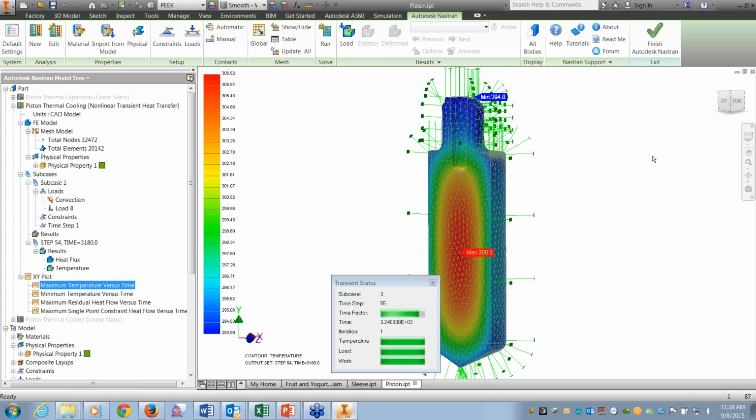So that relative clearance is important, both at the operating temperature, but are things going to jam up as the temperature changes? What happens if you've got a change in product that now might need to be packaged at an elevated or refrigerated temperature? And we go and take a look at those different scenarios.